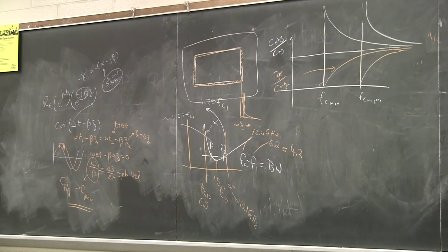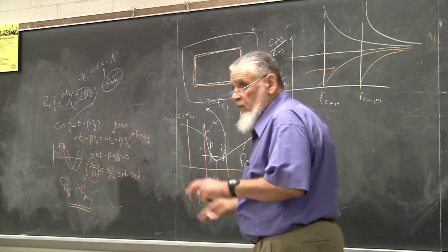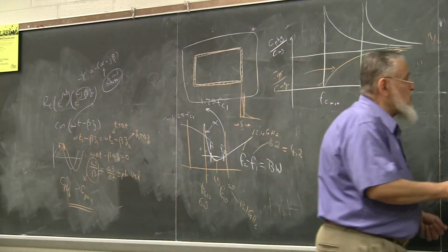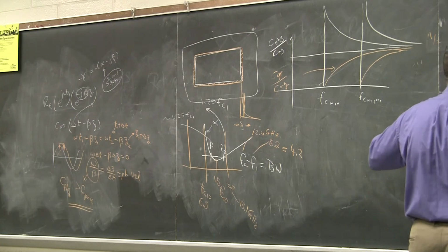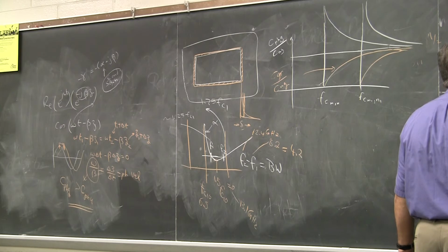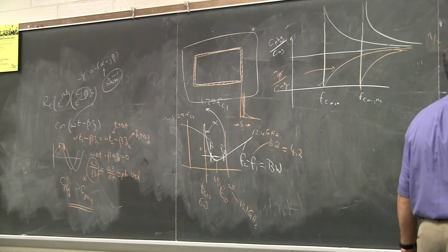And we showed over the cross section that the distribution will be doing these kinds of things, right? In other words, you have no propagation in the x or the y. And we assumed the propagation to be only in z, because we assumed the guide was extending. So we wrote the solution as e to the plus or minus j beta z.